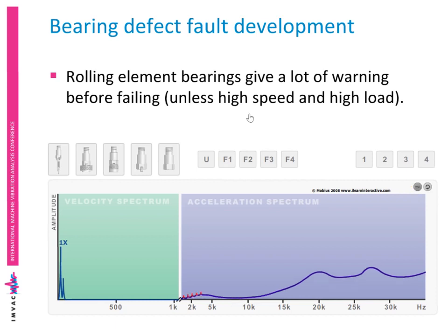But as the fault develops, if you continue to monitor it, you might notice that you'll see some of this higher frequency vibration get into the lower frequencies. And in fact, if you use enveloping techniques that filter both at the higher frequencies and at the lower frequencies, you'll notice that the higher frequencies will increase in amplitude first, and then the lower frequencies.